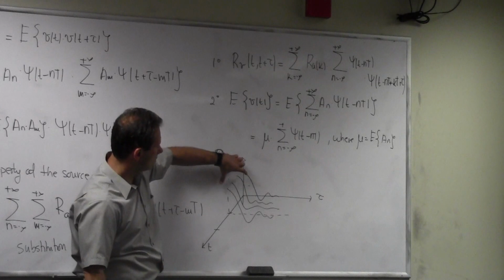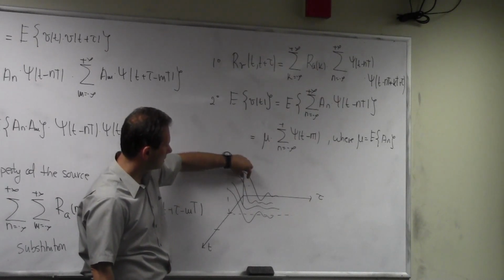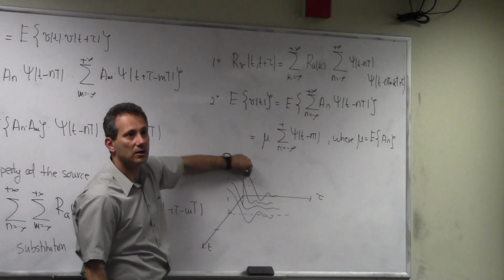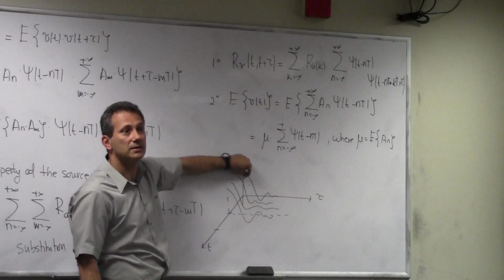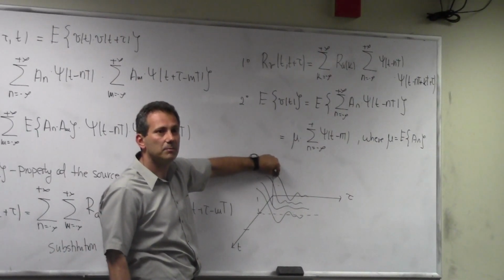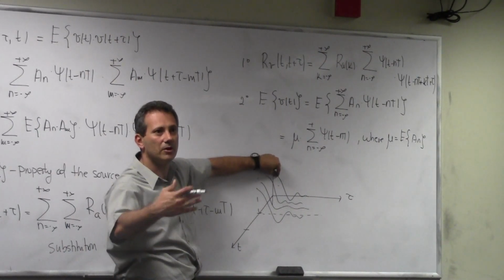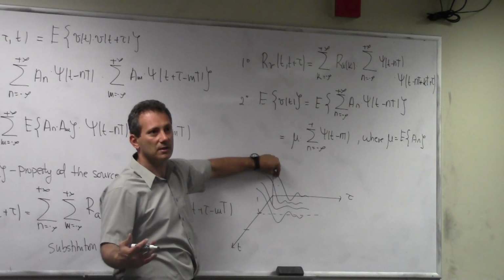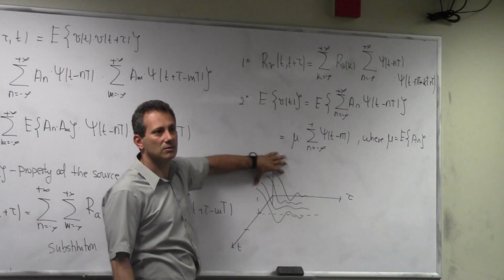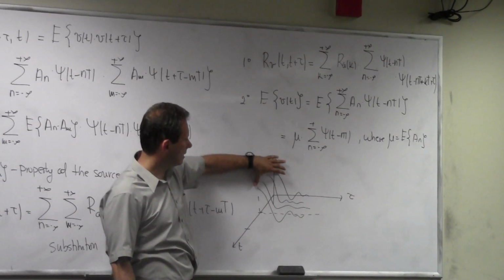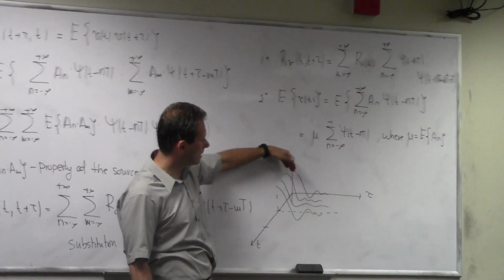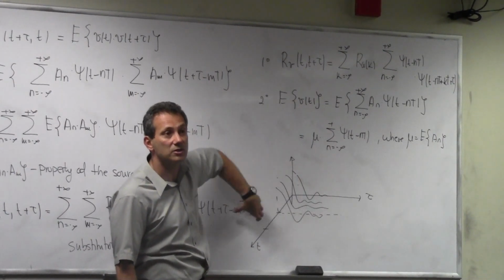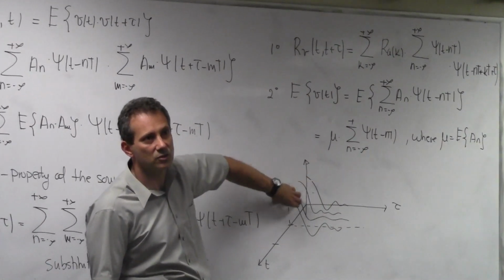So at every instant I can determine the Fourier transform of this autocorrelation function and get the power spectral density at this particular instant. But that power spectral density is also going to be periodic in time. So what I'm saying is, the average power spectral density, I'm going to average this over time. And when I average this autocorrelation, then I get the average autocorrelation function for this period t that does not change, that is now stationary. The average autocorrelation function does not change over time.